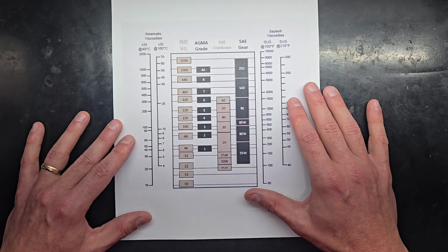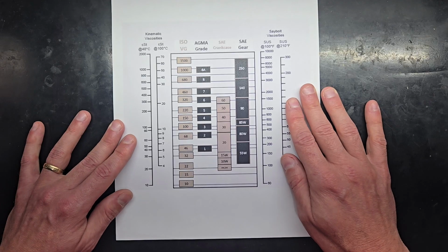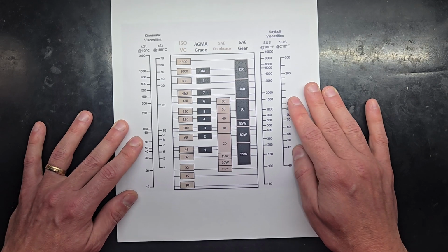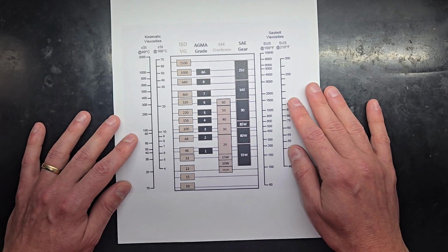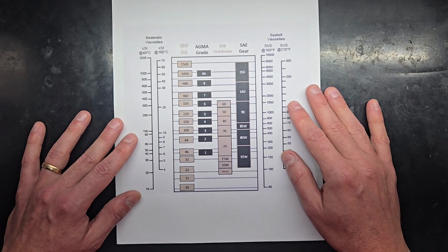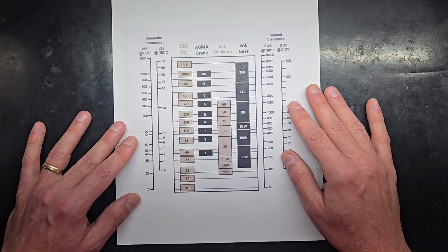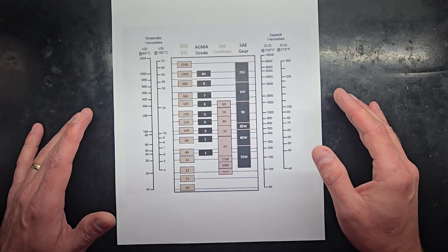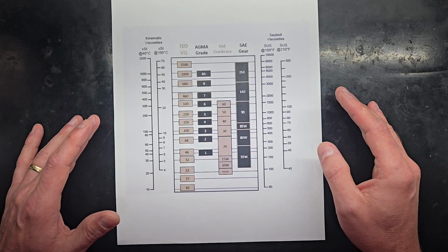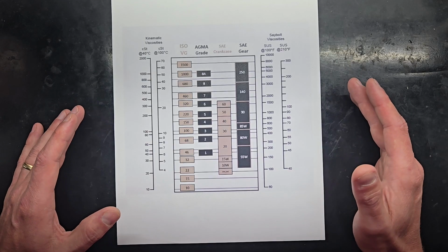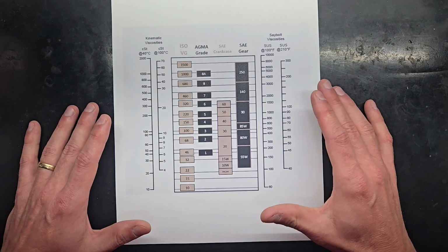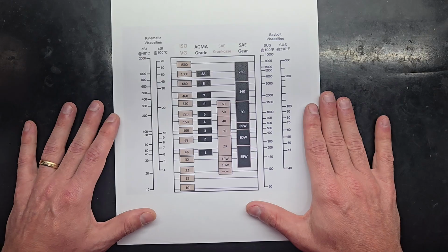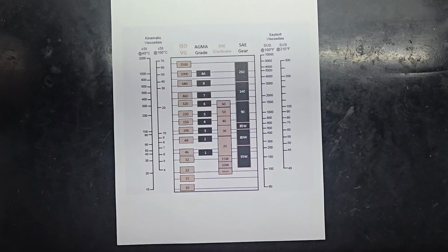So I'm trying to stress a little bit and try to start turning the conversation in our space away from I use a CLP or I use a generic oil, and get it turned to the product I use has a viscosity of 70 centistokes, 150 centistokes, or 10 centistokes. Sorry for mumbling. Because the viscosity is important, and I believe if we start looking at our products that way, we're going to be able to get more performance out of our firearms.